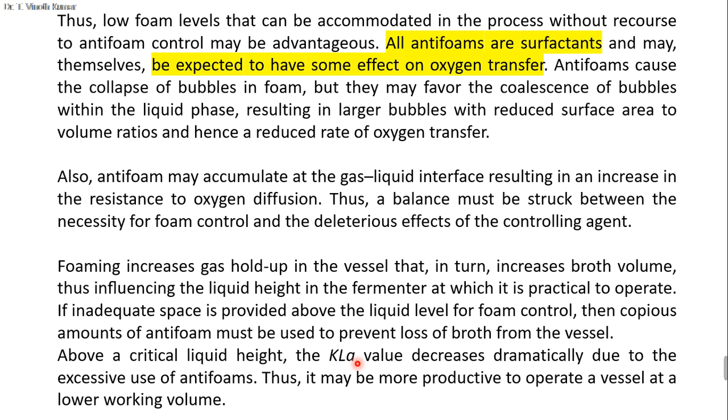But if you are using the manual one, without a mass flow controller, not an automatic fermenter, what will happen? By the addition of a few drops of antifoam agents, these antifoam agents may cover the liquid surface or liquid interface of the air bubble, and automatically disturb the KLa value. This KLa value is decreasing. That means the oxygen mass transfer may be disturbed here. That is why the dissolved oxygen level is going to decrease. So ultimately it leads to poor multiplication of the microorganisms and poor yield.